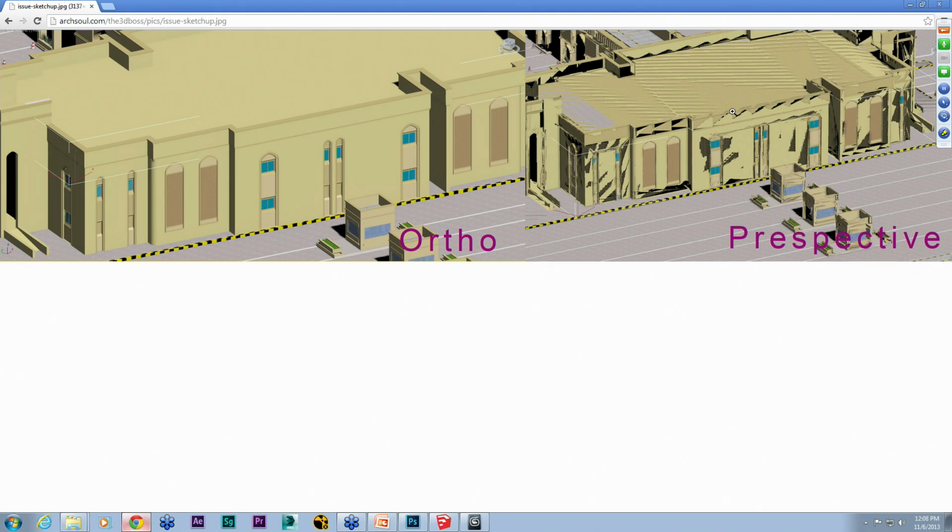If not, if I see this, the first thing I'm looking for is double geometry. And there are some scripts out there that help you sift through that. One is called Find Coincidences, which can help you find double geometry. But again, this is another reason why we do that 3DS, because this looks to me like a double geometry issue. It looks like a backface cull, I think. In object properties, you can turn it off and this will be solved.